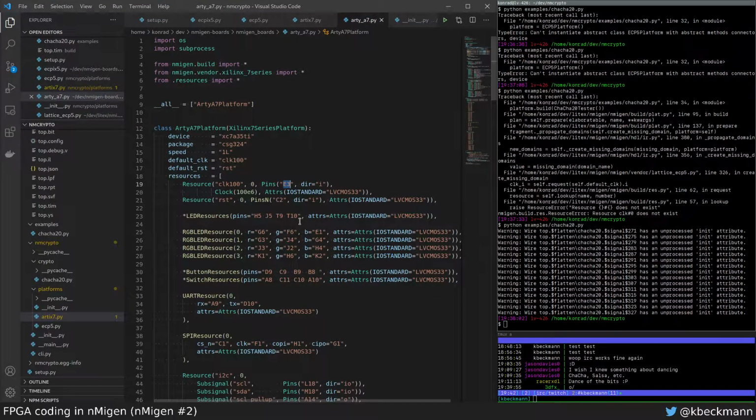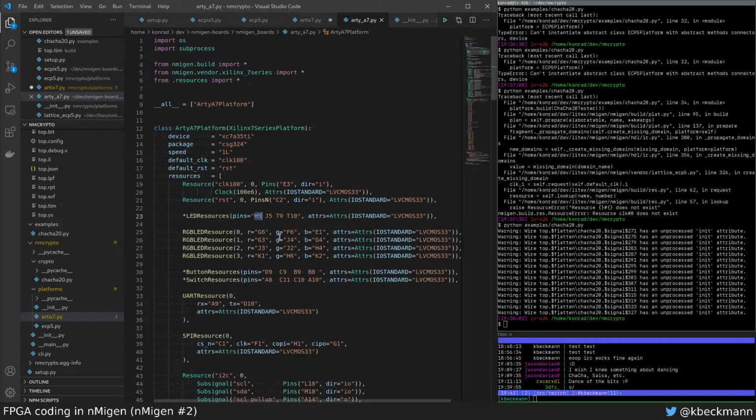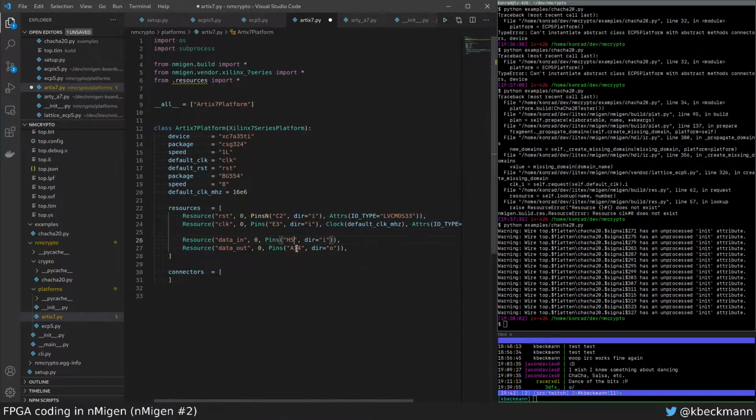Should be okay to do. So I'm just using some random pins. I have no idea if these pins are fast or slow or whatever. Who knows? Maybe they are on different IO banks. I don't know. It might matter, of course, because you can do better floor planning if you're in the same quadrant of the chip or section, I suppose. So yeah, I guess later on we can look at that. But right now I just want something.